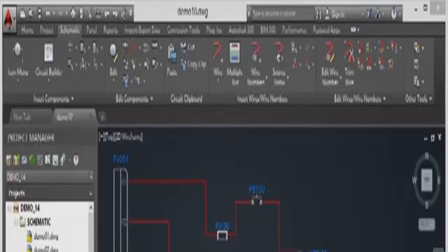Now there's nothing to stop me taking other wires off of other pins and flowing all the way around my AutoCAD Electrical drawing. So that's the difference between a ladder drawing and a point-to-point wiring diagram. I'm going from point to point here, just flowing around the drawing. A ladder drawing constrains you to that ladder and those rungs within the ladder.